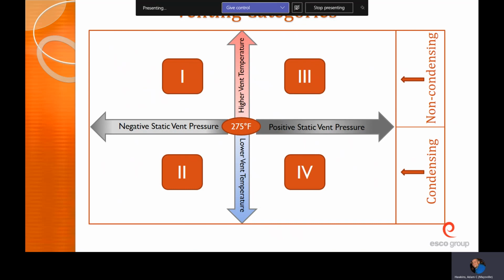That's your vent material. Whereas a standard efficiency 80%, you're going to have a higher vent temp, and so you're now looking at not condensing that. You're wasting more heat that a high efficiency furnace could have captured through a secondary heat exchanger, but it's letting it go outside. So as a result, you have more heat going through that pipe. If you run that furnace, and I think there's a video on Blackboard, or that you can find, I found on YouTube, a guy actually put the PVC pipe on an 80% furnace, and within just a few seconds, that pipe just completely melts down.